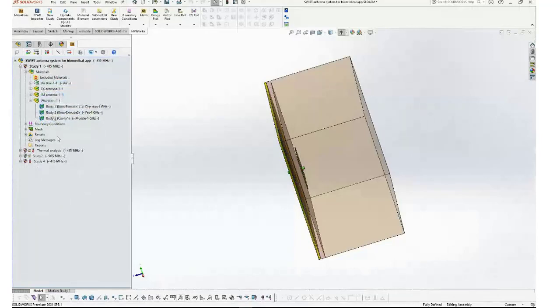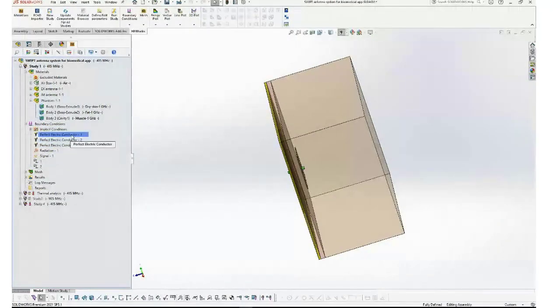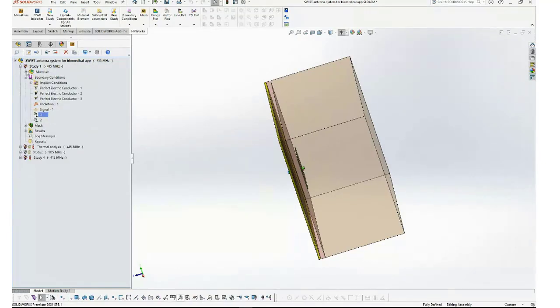So everything has materials. And then we needed to define some boundary conditions. There are boundary conditions that the software figures out automatically. If you use copper, it knows it has an imperfect conductor boundary condition. And then you can apply others explicitly. In this case, we said that we might have some leakage of energy, so we put a radiation boundary condition. And then we had some ports, port excitations. That's where we send the signal in and where we measure the signal out. So these are the boundary conditions.